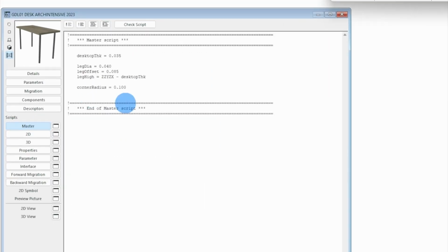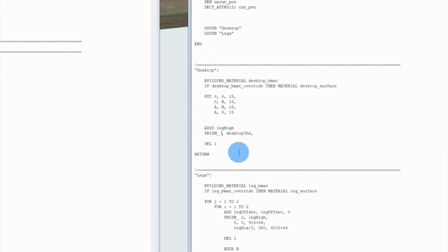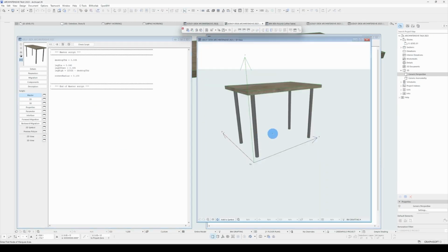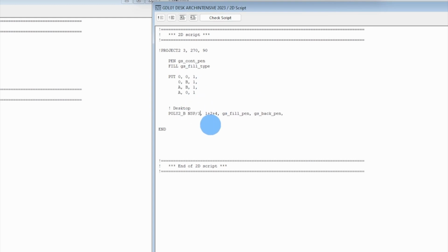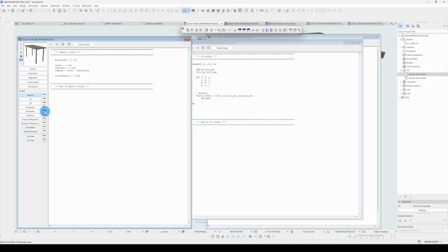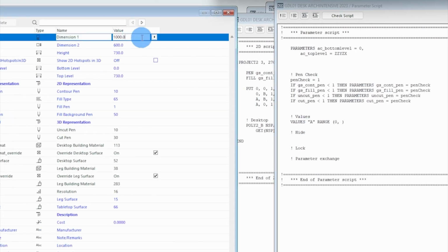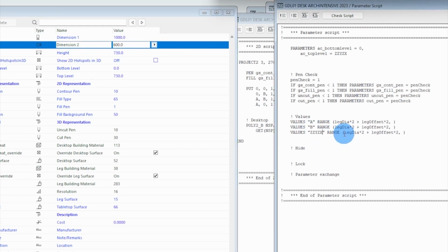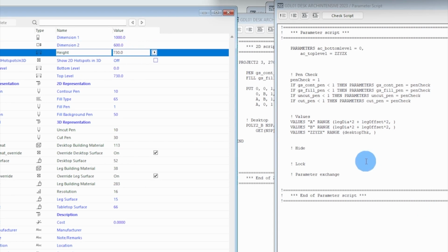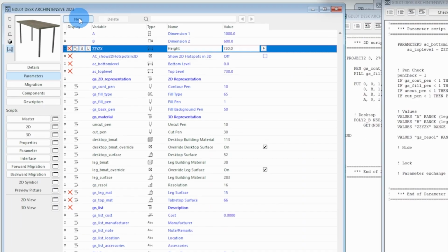Now let's put in the corner radius option. So I'll put command, tells Archicad, remember these numbers until I ask for them again. And the get NSP says, use the numbers I asked you to remember. So this is a way of inputting different coordinates for different selections without changing the final command. I'll add in some limitations to the values that the user can enter so that they won't break the object by entering in invalid numbers.